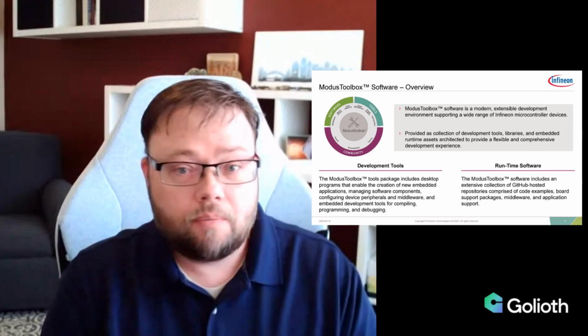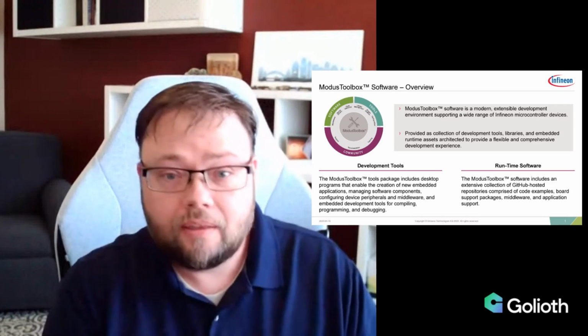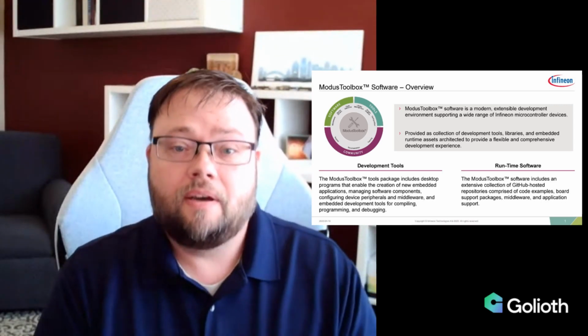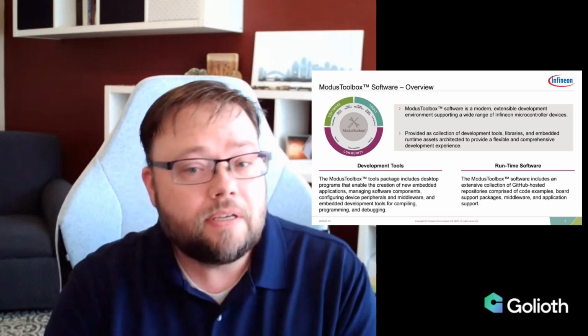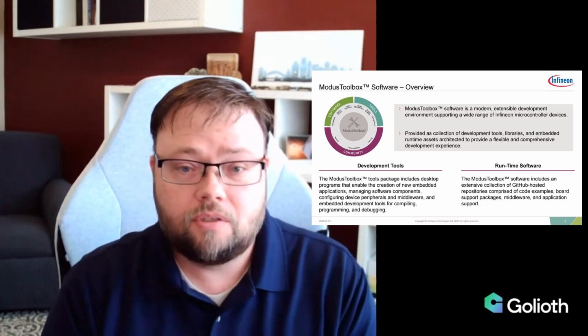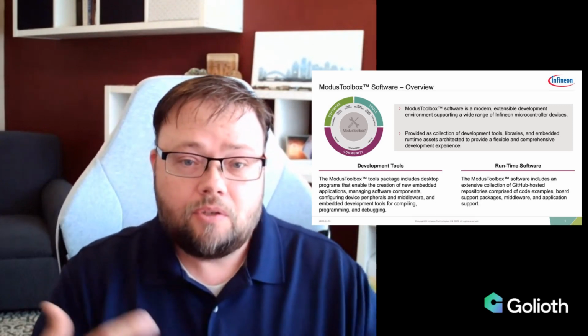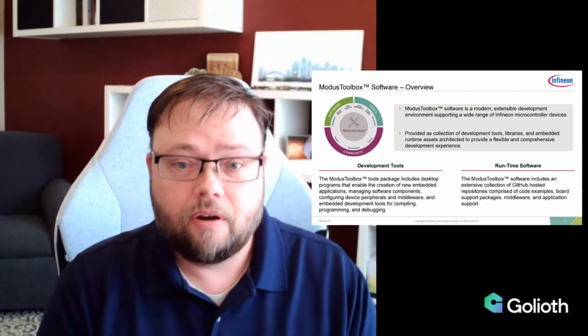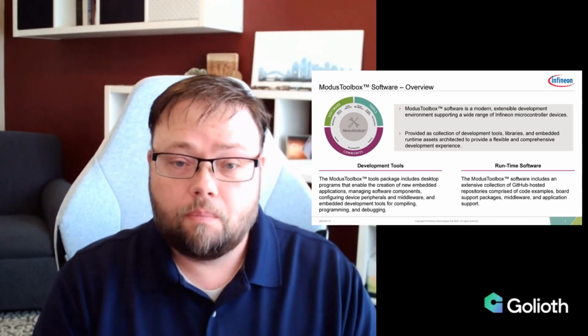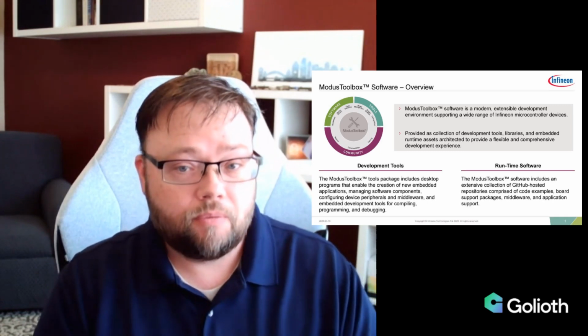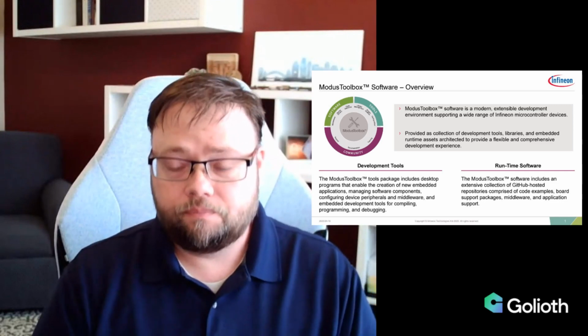You'll have applications that will help you with being able to create a new application. You'll have tools that will help you with managing the software components. So bringing in different libraries, bringing in the Golioth SDK into your application, configuring how you want to use the device itself. So setting up the peripherals. I need to interface with this sensor over an I2C channel or a SPI channel. And in those type of initializations of the hardware itself, there are tools there to help ease that, right, to help generate code for you, to initialize the devices, the peripherals, and on through the middleware itself.